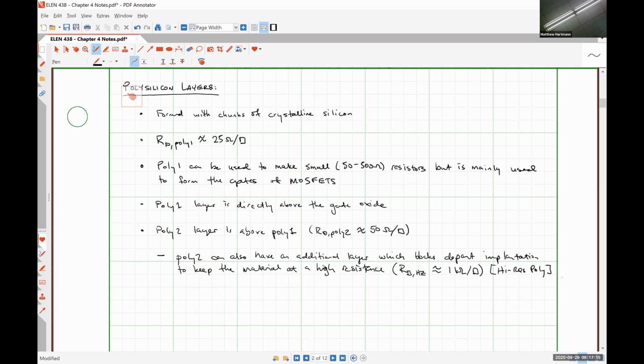It's going to potentially change the sheet resistance a little bit as well, because the thickness of the well, there's going to be an area of it where there are no free charge carriers if we make the depletion layer larger, or it's going to have more free charge carriers if we make the depletion region smaller.